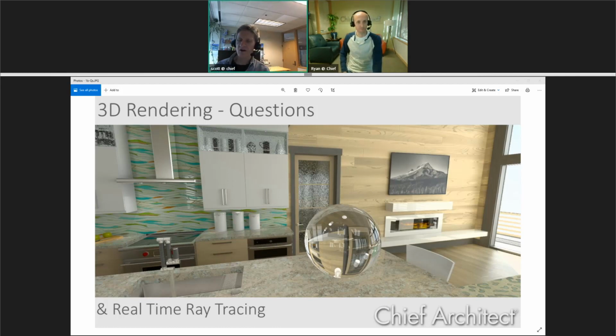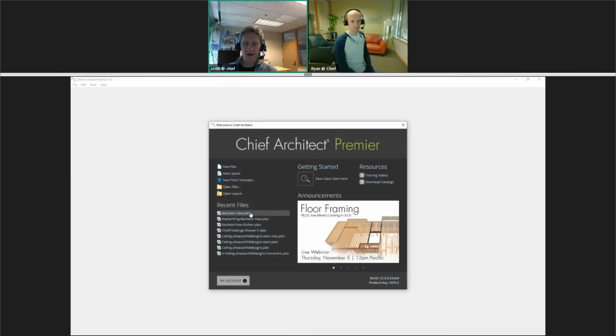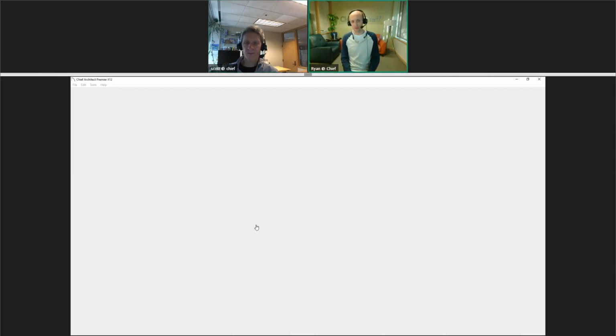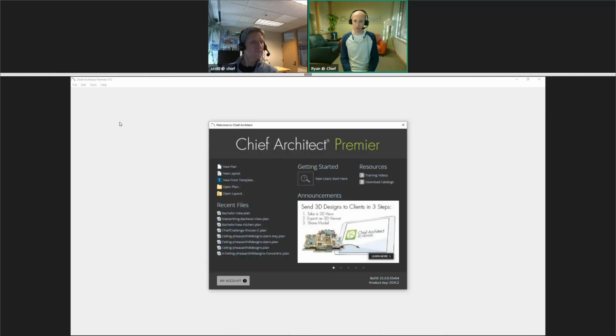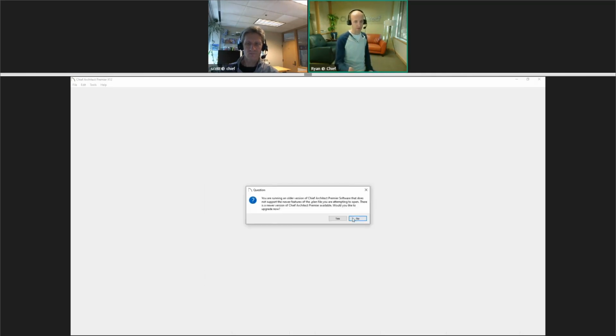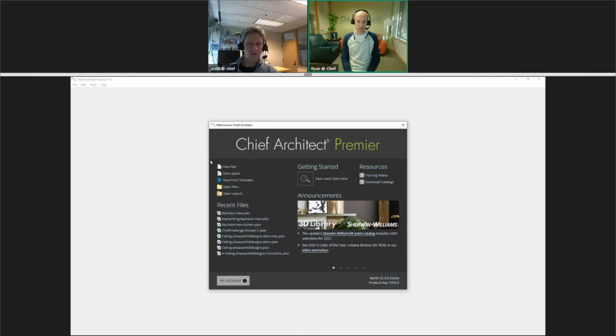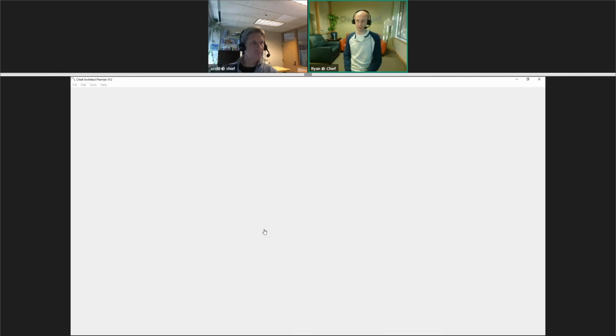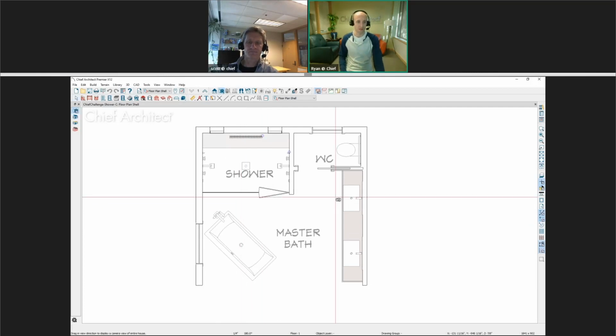Austin, do you use the current option for panoramic backdrops today? I do not. Okay. So there is an option for your backdrops today to support panoramic, and you might at least look at that, and then maybe I'll let Ryan weigh in on anything else about how that might work. So I don't think there's any really significant changes to the way that backdrops are going to work in X13 at this point. But I would definitely say that if you have a panoramic image, the panoramic tool works pretty well. If you go into your backdrop and you make it panoramic, then it will essentially wrap around your house. In particular, if you have an image that is actually a panorama, that should work pretty well as is.